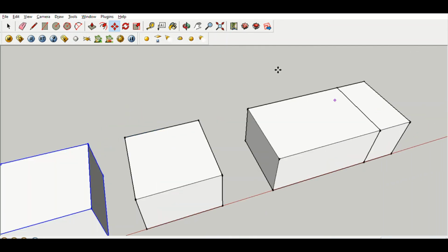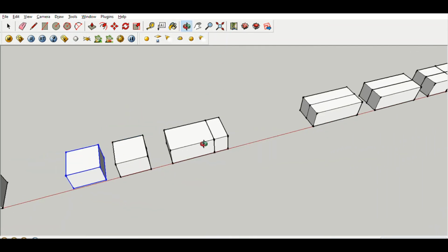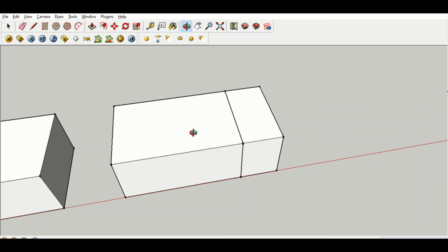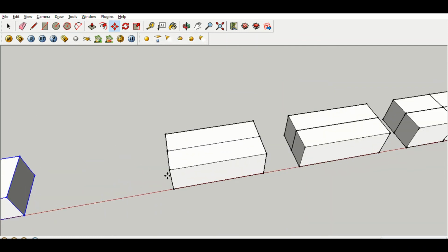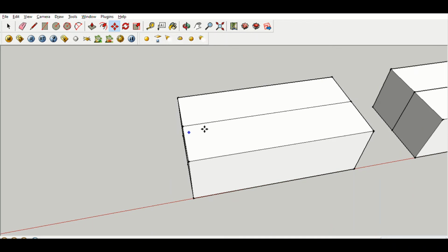If we cut the brick from 1/4 part, you will get what? You will get 2 equal parts like this. This will be called quarter bat, and this will be called 3/4 bat. If you cut the brick from the stretcher surface, along this stretcher surface like this, okay, what you will get?